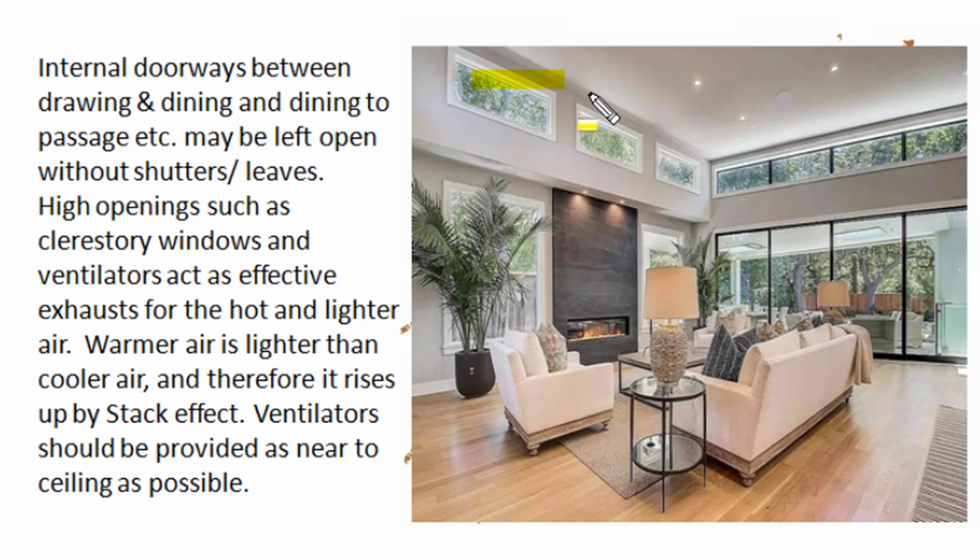High opening such as clerestory windows and ventilator acts as effective exhaust for hot and lighter stale air. During building operation, warmer air being lighter moves up, and when it escape out from ventilator or clerestory window, then from bottom side cooler air naturally come inside, and by heating, when air become hot, it rise up and goes out from ventilators, and this effect is called as stack effect. And for good stack effect, ventilator should be provided as near to ceiling as possible.